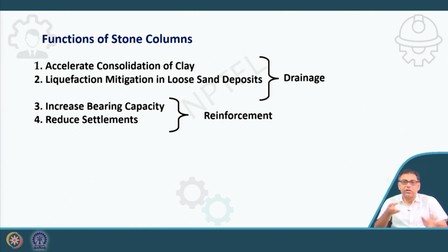In consolidation, the permeability of clay is very low. So if I install the column, it will provide a drainage path so that the consolidation time can be reduced, for faster consolidation. Similarly, in liquefaction it will provide a drainage path so that the excess pore pressure generated during or after the earthquake can easily dissipate from the site.